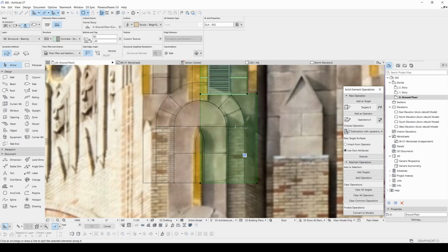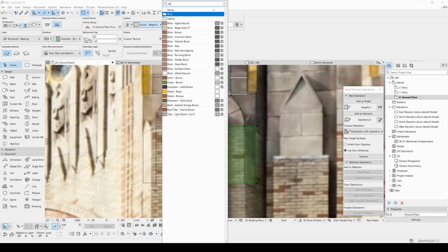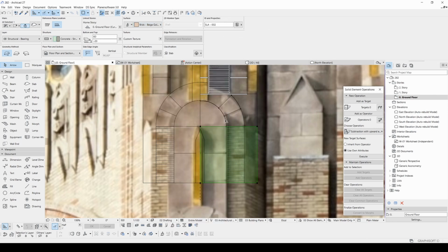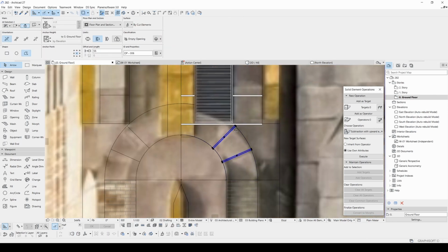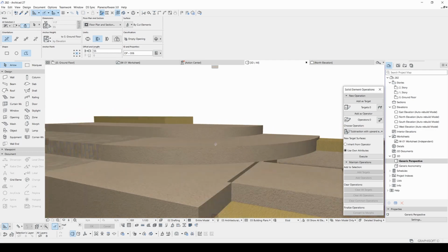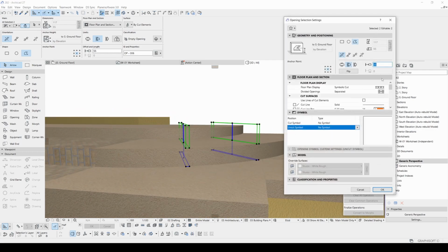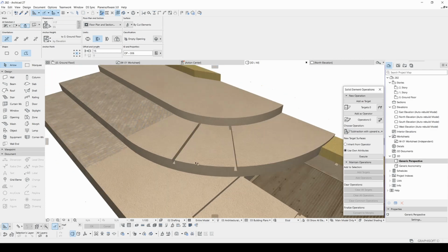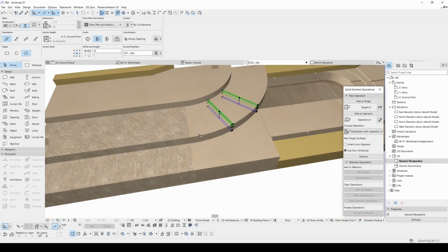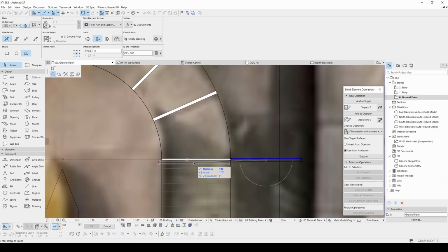I think this part will be brick as well. Now I'm going to select them in the 3D window, and I will change the value to 50. Now it works. We are going to hit this inner point, and after that we will click this cut additional segment elements.